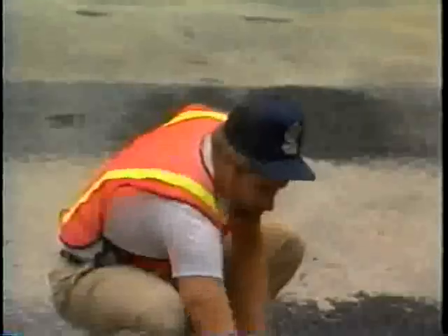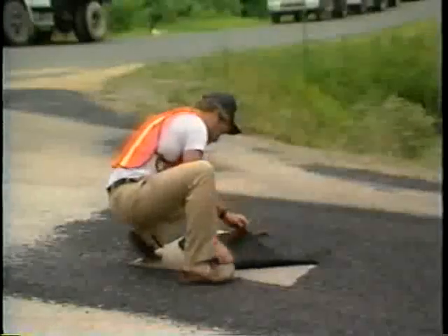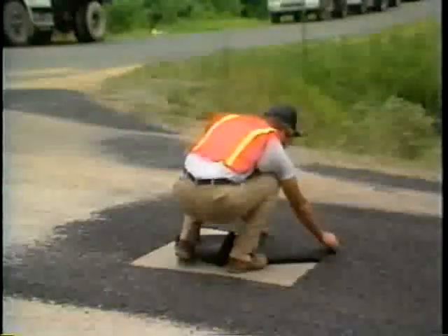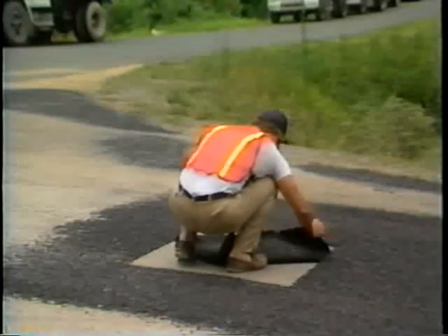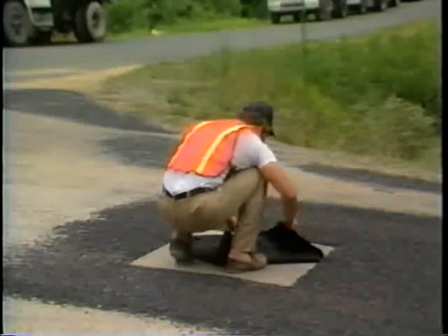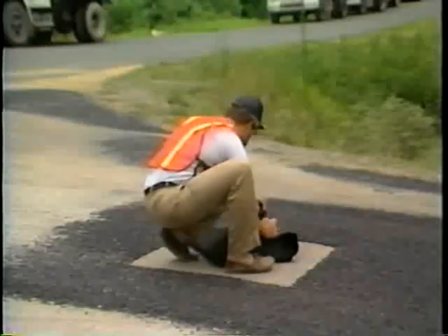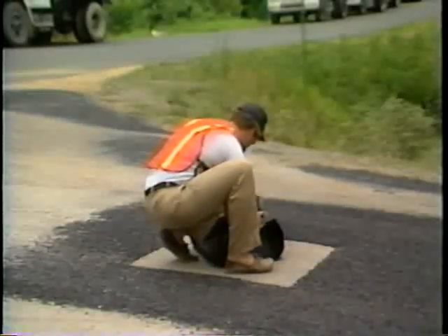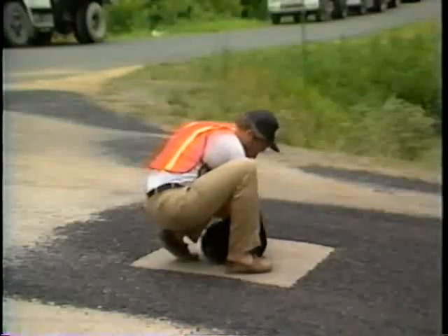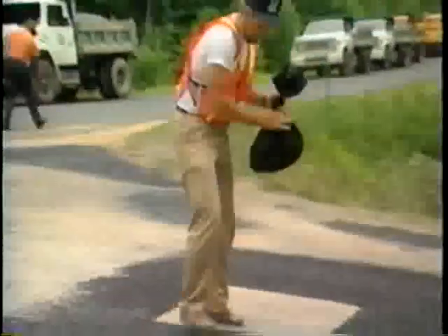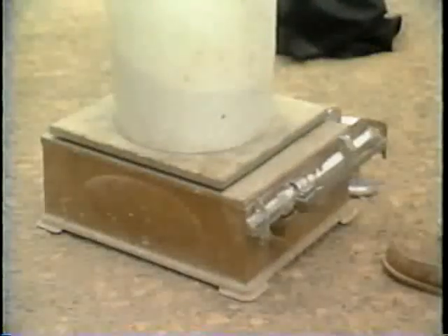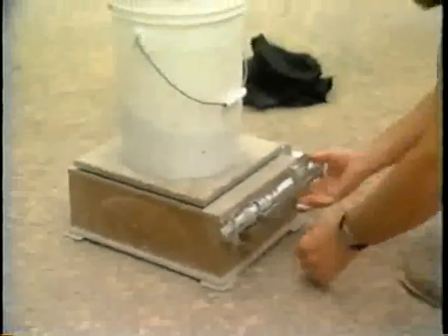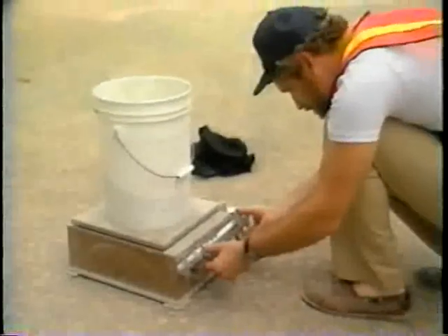operation. Aggregate application rates, like asphalt application rates, can be calculated using a formula or taken from tables. Make a quick check on the amount of aggregate being applied by laying a 1 square yard section of cloth on the ground and passing over it with the spreader. Then carefully lift the cloth and the aggregate and weigh them. This will give the application rate of the aggregate being spread.